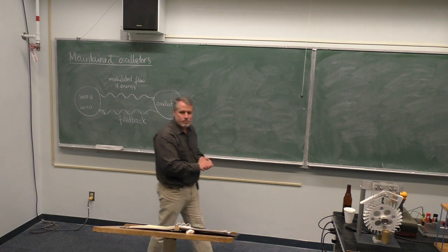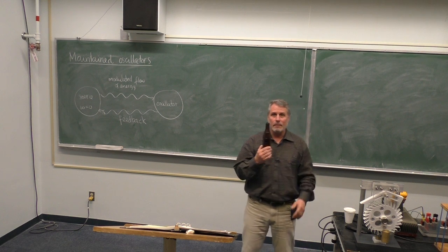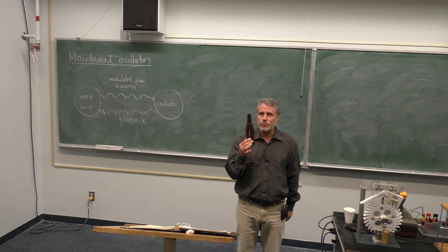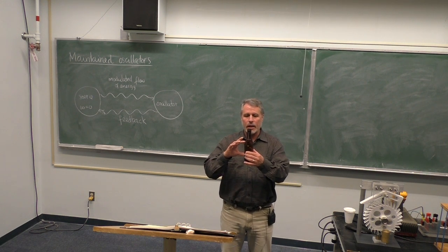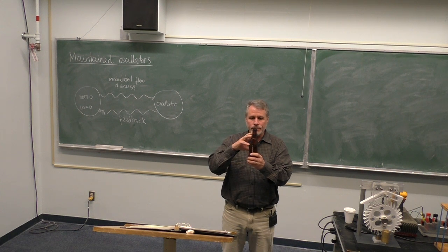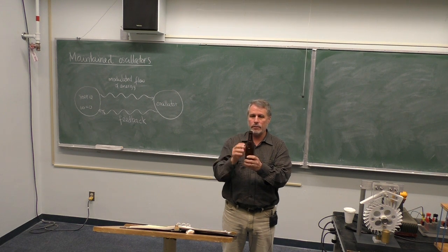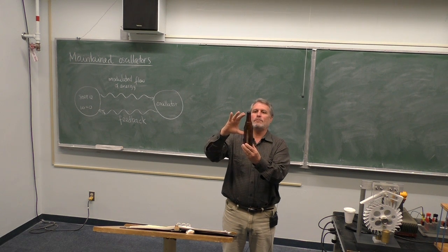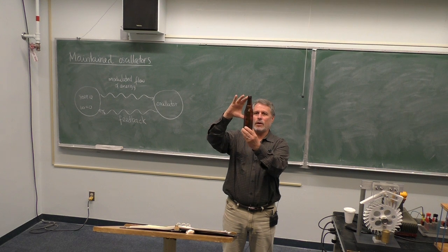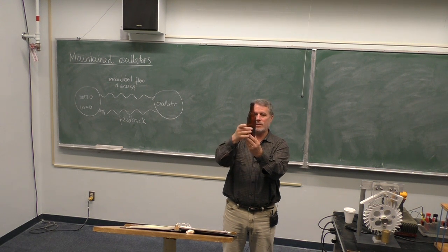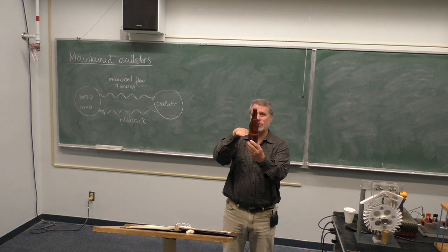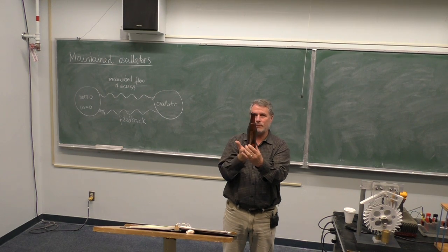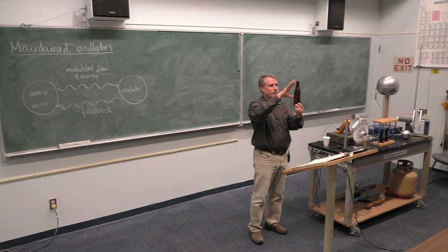A very simple example of this is what is called the Helmholtz resonance, the Helmholtz resonator. A Helmholtz resonator is a fixed volume object that also has a neck. In this case, that's the neck of the resonator. The volume for this particular Helmholtz resonator is the volume within that column. I have put water there, so water is seen as stiff, like a rigid termination right there, as if I had the bottom of the wall of the bottle. And so my volume is the volume in that particular enclosure, and I can excite